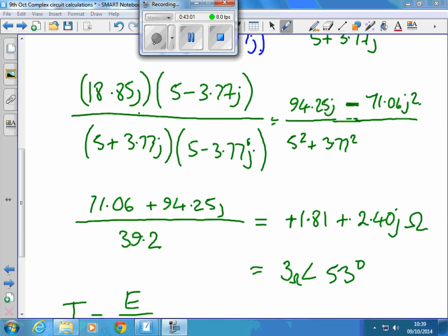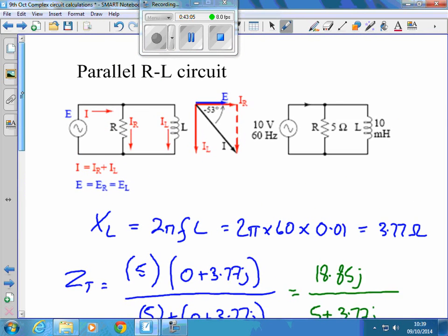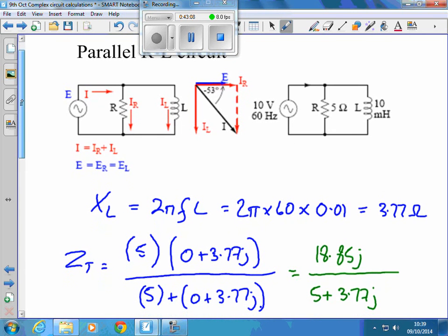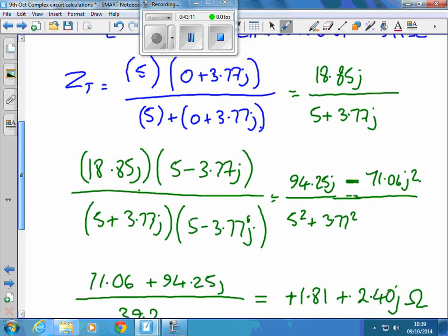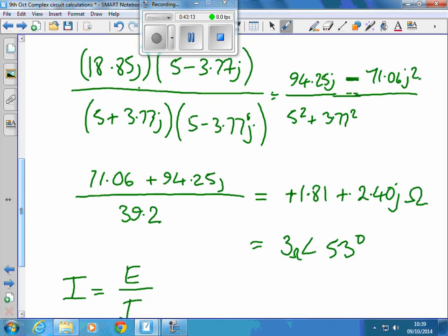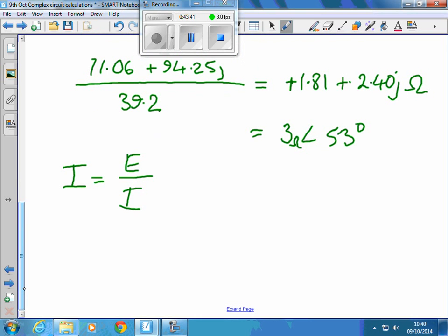I noticed that by going back to the original phasor diagram and knowing the circuit is inductive, and therefore the impedance should have a positive angle between 0 and 90 degrees. It can't go beyond the 90 degrees of a pure inductor. So the 127 degree angle was an immediate flag that something's wrong. See how getting one positive or negative sign wrong can get the answer totally wrong.